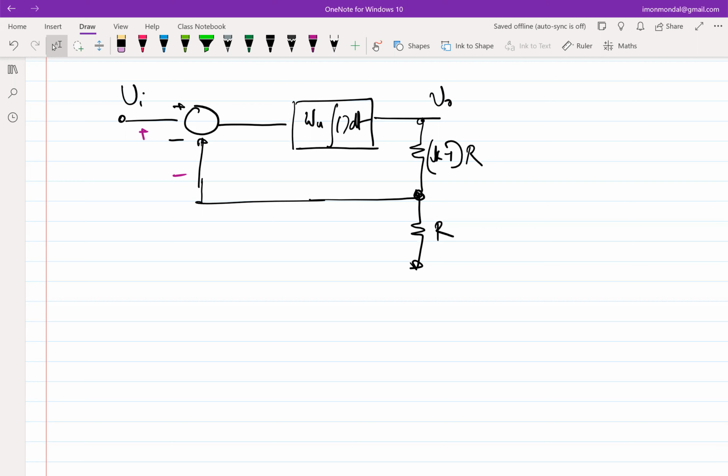Right, exactly. So that's the main conclusion out of it, that you can have zero input and finite output, but what the final output will be doesn't depend on the integrator. It depends on whatever you have wrapped around it. So this input will be zero regardless of whether Vi is a 1 volt step or 2 volt step or 5 volt step, doesn't matter. If you wait infinite time, V will go to zero, but V0 will be K times 1 volt or K times 2 volts or K times 5 volts, depending upon whatever is wrapped around that integrator.